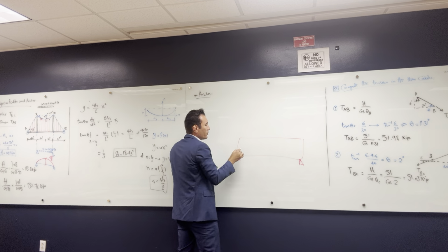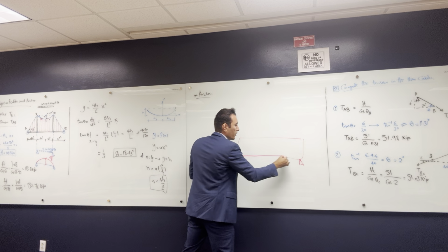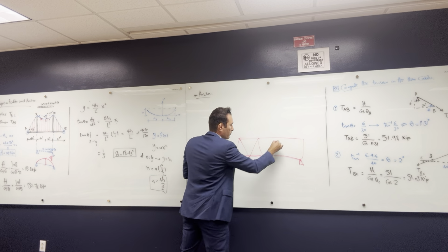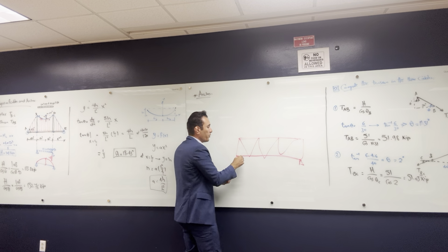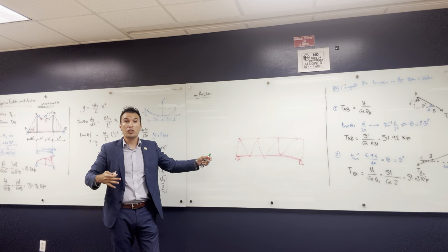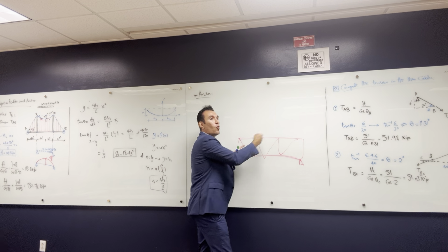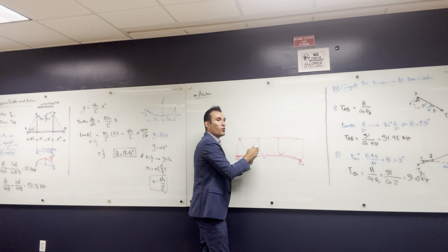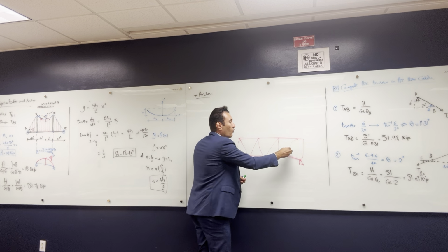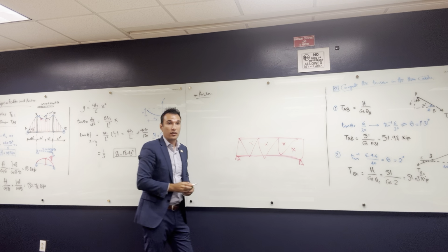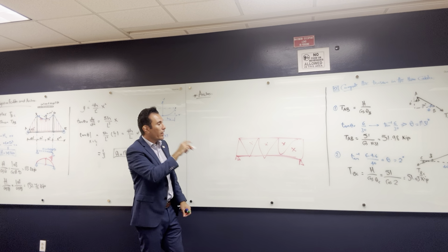So what you do, you say, okay, what I'm gonna do, I'm gonna put steel here, I'm gonna put a steel here, I'm gonna put something like this. And when this truss bends, all this is gonna take tension, all this is gonna take compression. So the truss takes the tension and compression and utilizes all the material that we have, okay? And we put cross members to make the truss stable. So that's why I didn't waste the material that I have here from the concrete section, okay? All right, that's one system.